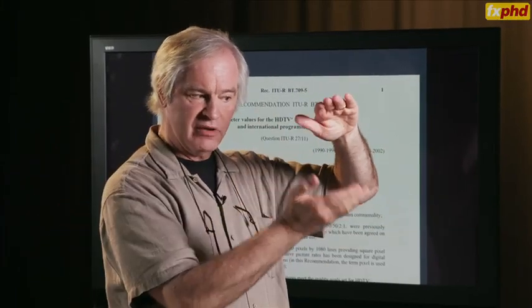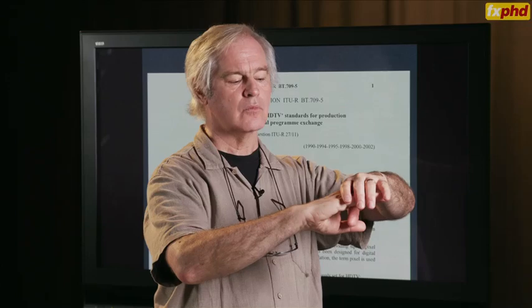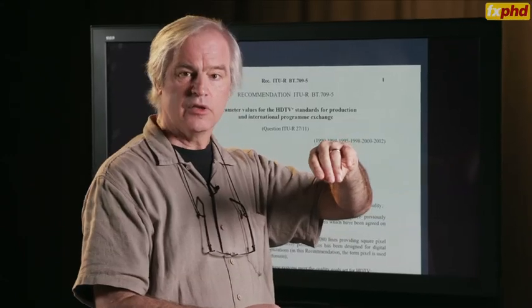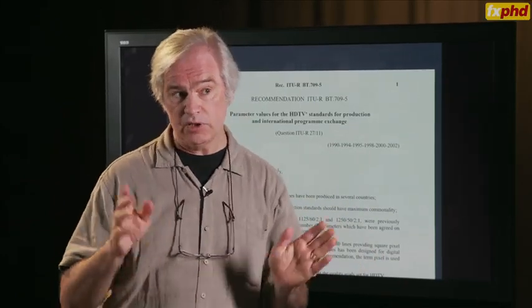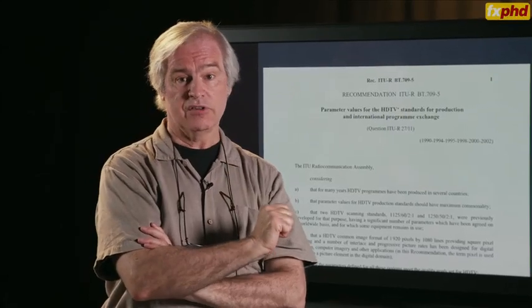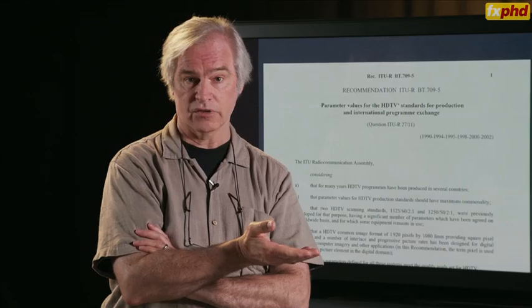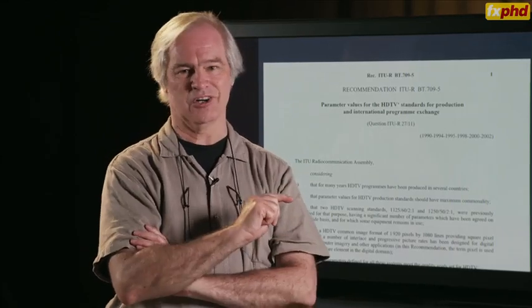Roughly speaking, the way we can adapt the image data to these different environments is by changing the gamma. HD, I've explained, has a gamma of 2.4. To go to a really dark environment like the cinema, to achieve the correct image appearance, you'll want to increase the gamma a bit to about 2.6. Well, DCI, or the SMPTE 431-2 standard, the standard for cinema presentation of digital material, is gamma 2.6. It's not 2.4 because it's way darker.